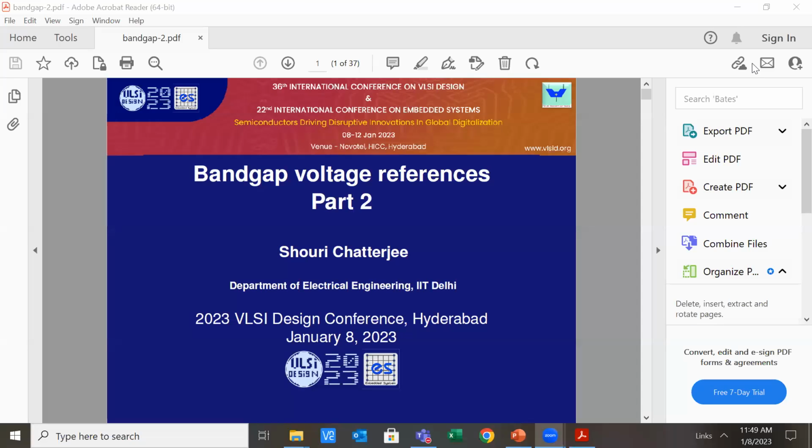Take a capacitance of roughly 10 pico, and the zero is close to a megahertz, so your bandwidth is far higher than that. That means you have settling in a couple of microseconds.